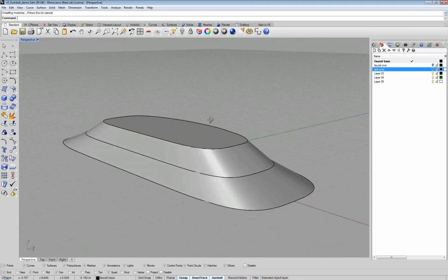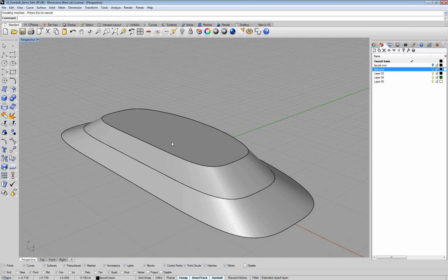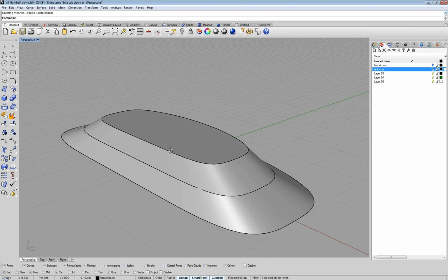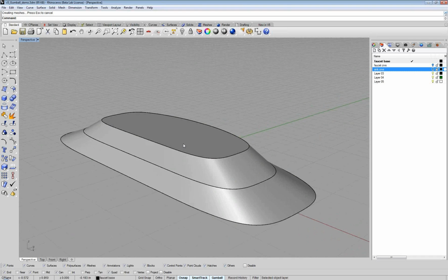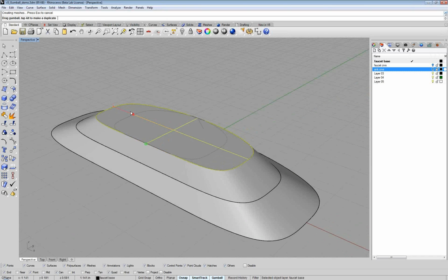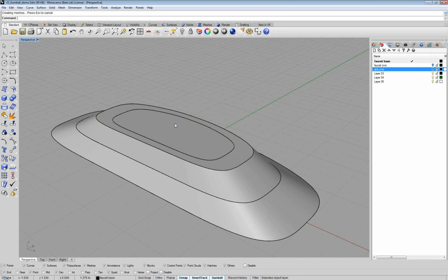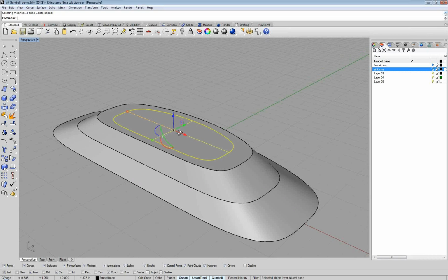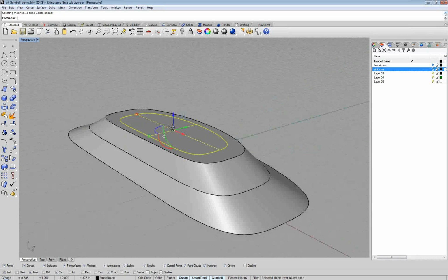So I want to make a little tiny relief on the top of this base. I want an indentation rather than a positive form. And sometimes in order to go down, you have to go up first, and that's what I'm about to do. If I Control-Shift sub-object select that top face, start to scale it in, hold down Shift to make it a uniform scaling, and then tap the Alt key, I'll see a plus symbol. I'll then release the left mouse button. I'll deselect everything, and now you can see that I've copied that face through the scale operation.